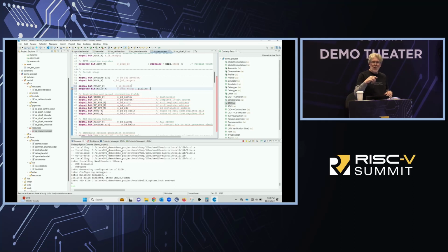And that is the reason why I created the first multiply operand as no-op. Because when I clear my pipeline register, everything will become 0. So I really want my operation of my multiplier not to occur if that ever becomes 0.